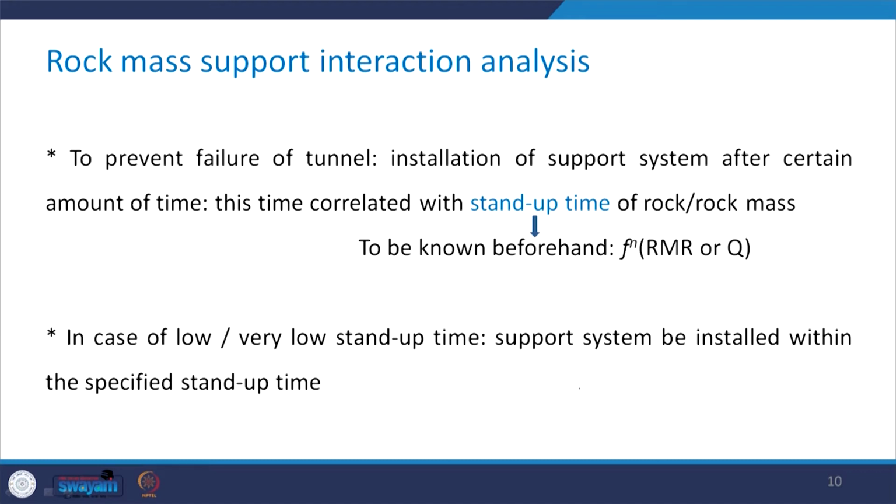This time is correlated with stand up time of rock or rock masses, which is to be known beforehand because it is a function of RMR and Q. And if you recall our discussion when we were discussing about this systems RMR or Q, we saw that based upon the value of RMR or Q, we can determine the range of these stand up time. There were various tables which were available.